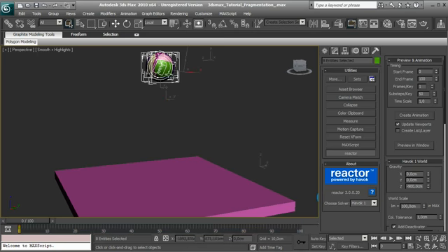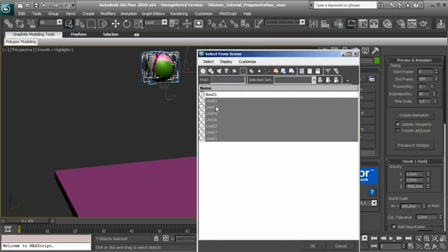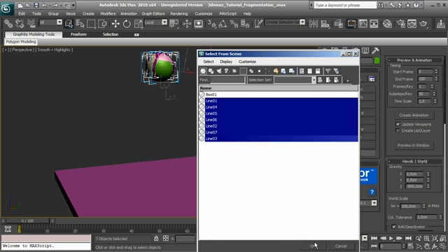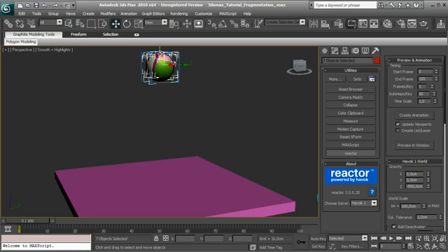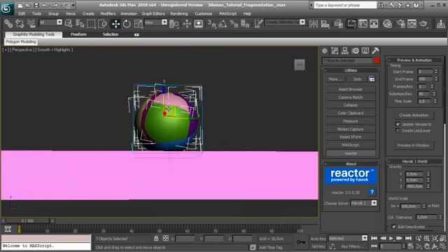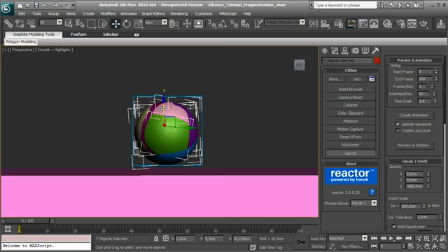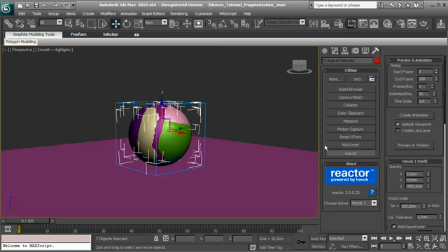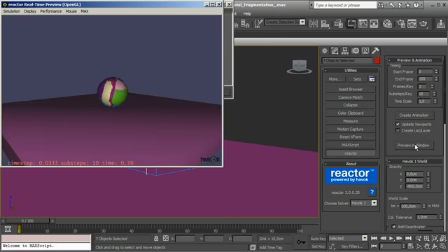So I select all the mesh, I select all the pieces and I move them over the box, and we can go again back to 10 sub-steps, and let's see a preview. As you can see, the sphere will just move and we have no breaking events,